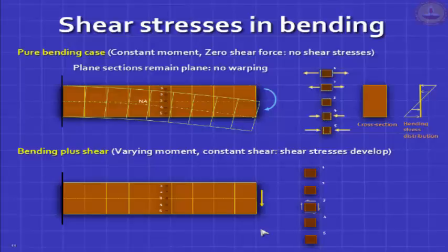And you have complementary shear. So shear can happen in both directions. You've studied this. At the neutral axis location, you will have only shear. You don't have any normal force. And what does this shear do? The shear is going to distort that section. The rectangle will no longer remain a rectangle. It will warp. It will get distorted. And you can see clearly that pure shear is a case of one diagonal getting extended and the other diagonal getting contracted.